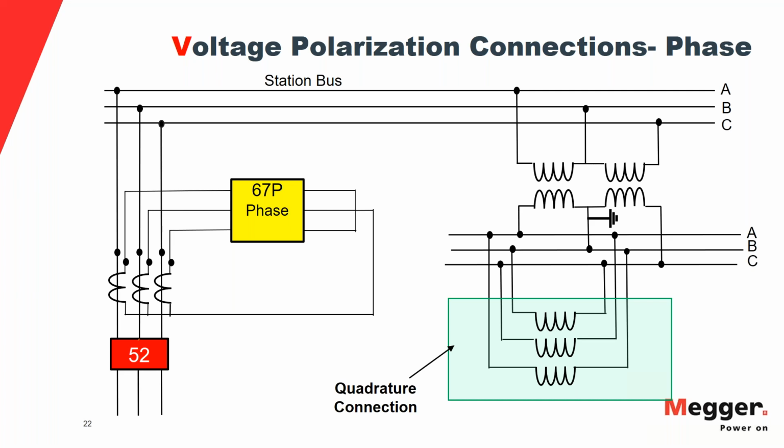Yes, memory voltage changes. There are two different types of relays in the market, electromechanical relays and numerical relays. In electromechanical relays, the manufacturer uses a capacitor inside to keep the last operated voltage as a memory voltage. That gets changed every time the voltage in the power system changes where the relay is connected. In modern numerical relays, the last recorded fault voltage is the memory voltage. That can also change, but it never changes every time, only when there is a transition of fault. It's not like minutes or hours.